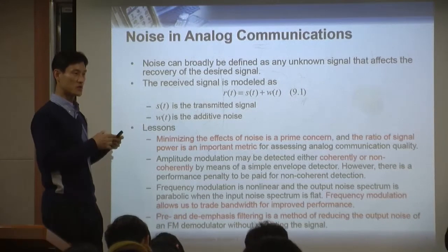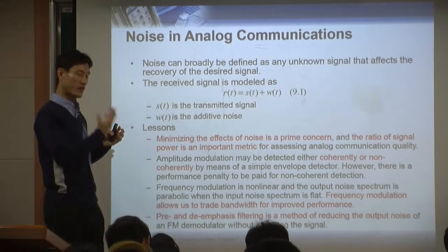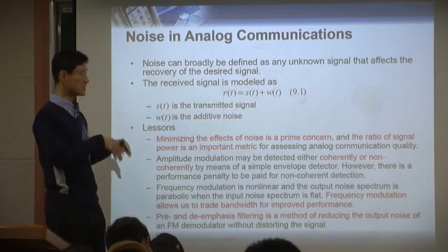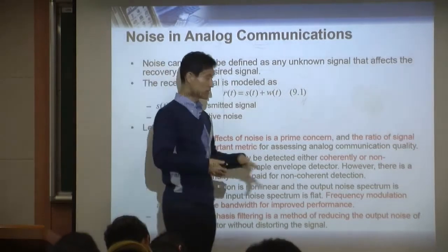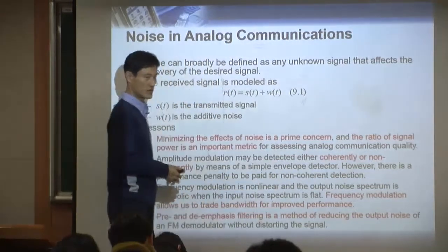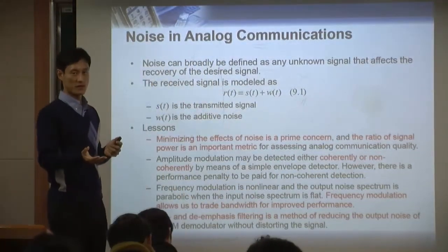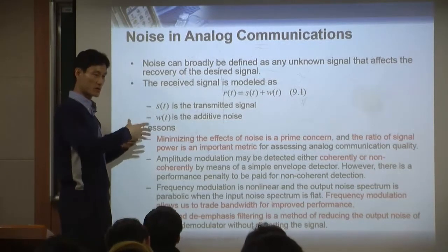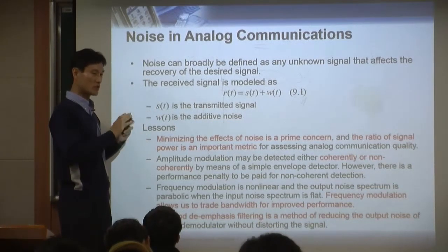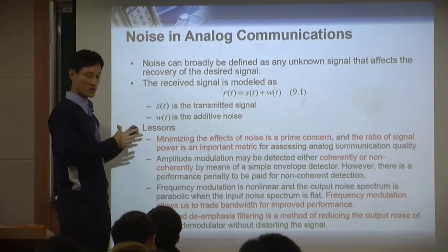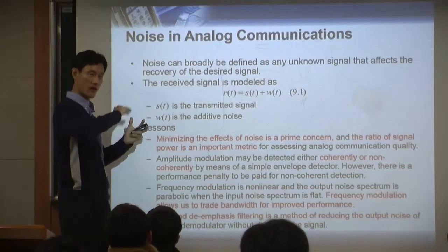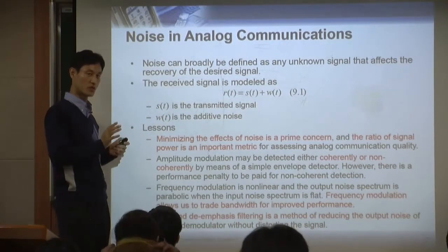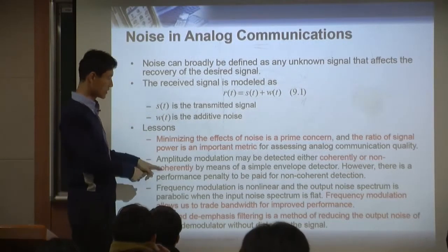Costas receiver eventually wants to find out the phase and you want to correct the phase, right? So Costas receiver is still a coherent detector. But a non-coherent detector is something like an envelope detector. Think about the envelope detector. It basically works and you don't need to know the phase. Envelope detector works just based on the envelope detection. It has nothing to do with the phase. You don't need to know the phase, right?